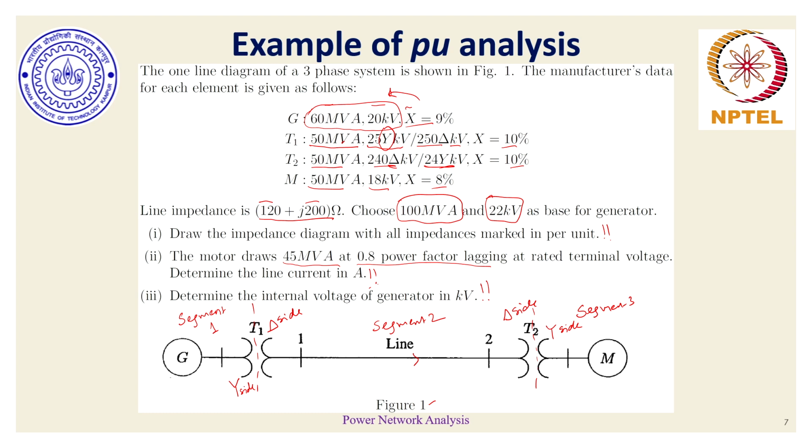Now, if this circuit had transformers T1 and T2 with similar configurations, let's say star-star, the overall analysis would have been very simple, and probably there would be no need for this per unit analysis. Since these transformers have dissimilar configurations, the per unit system will definitely help in analyzing this circuit. So let's see how the per unit system helps.